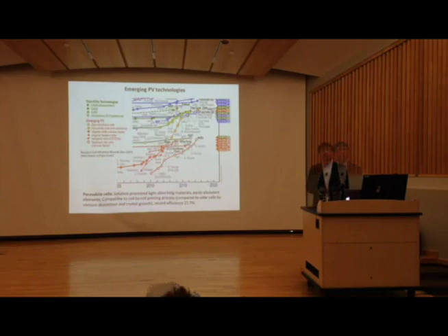Being an instructor and installer, we've talked with some of the fire departments, and what we found out, like a couple weeks ago, there was a big meeting with some of the department guys, and as to the answer to your question, a lot of the arrays are on one side, the south-facing side. We were told by the firefighters that when they come out, they just won't go on that side. They'll go on the other side, the north side, and open up their holes where there is no array, where there is no problem with that.